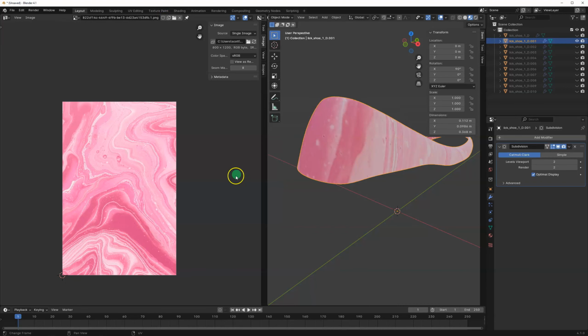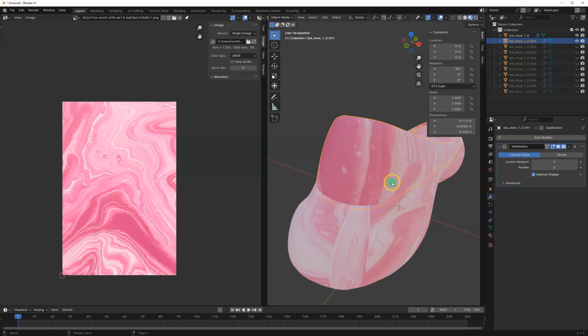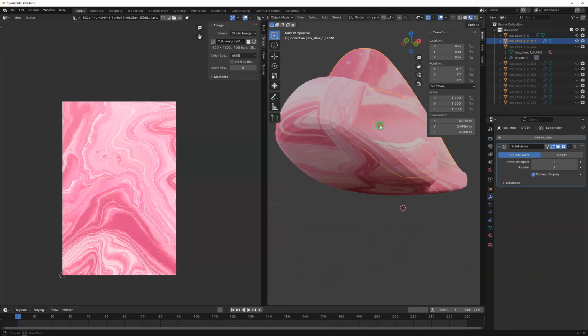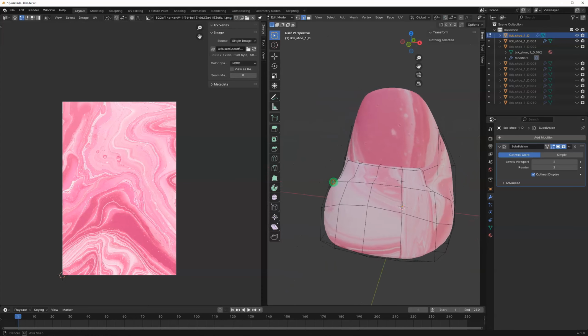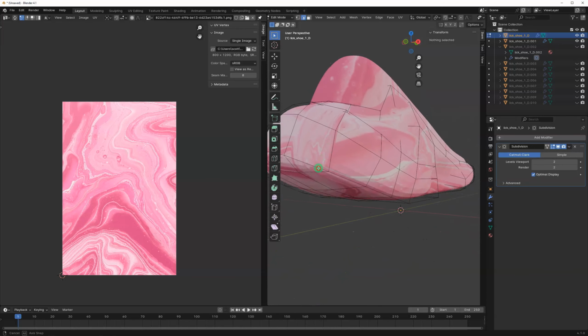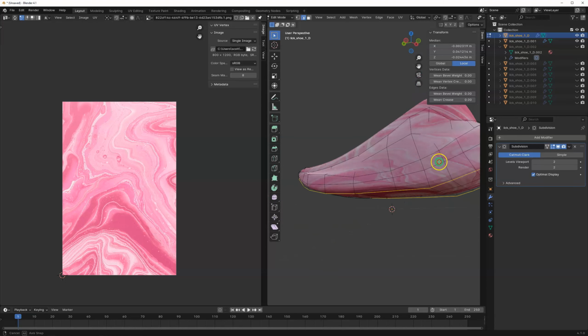Let's just press Tab and let's turn on the sole. So there's the sole. I don't really like how that's the same material, but anyway. And yeah, you can see how we can start to fix things. So if we look at this object here and go Tab, we can start to try and get the UV mapping working well. So what we might want to do is go Alt and click here and select that whole bottom island.